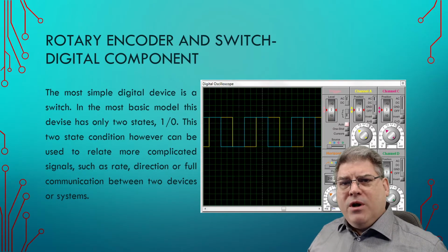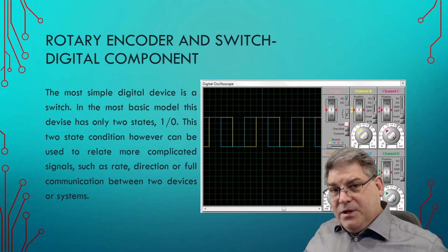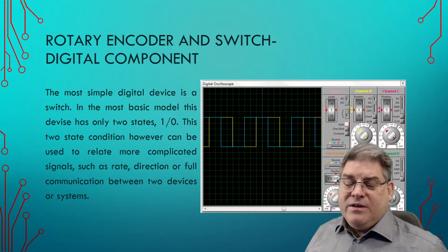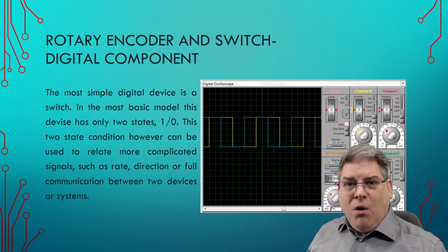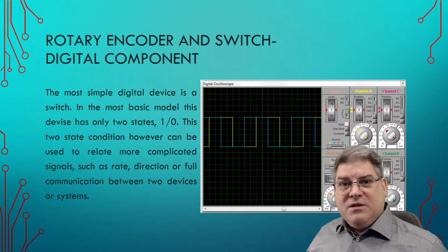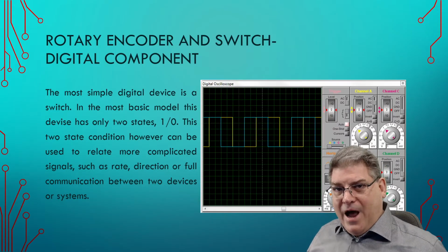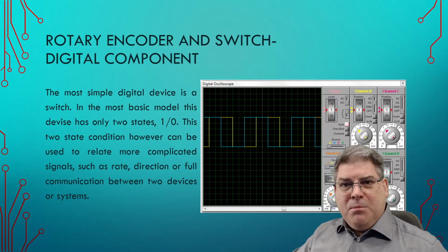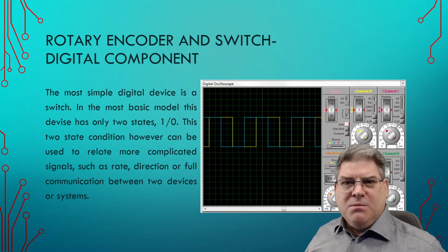Whereas the rotary encoder, if you think of the knob to adjust the radio station on your radio, you can twist it forever and you never really hit an end stop. And that's because it's just simply sending pulses. And once it reaches a maximum value or a minimum value, it's done. It's hit its limit. And you can turn all you want. It's not going to do anything. These tend to also be more robust because there's nothing mechanical actually happening. So we don't have, in the case of a potentiometer, a wiper running across a piece of carbon on a disc. Okay, so as far as longevity, much, much longer.